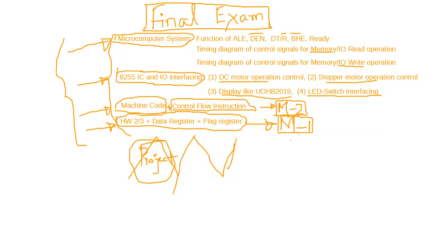We have to convert it to digital, then scale it down, and then we control the LED on and off according to the value of the sensor data. Same thing for the DC motor control, which is speed control. Speed will be low or high depending on the analog data. For example, if the analog data is low, the speed is low.